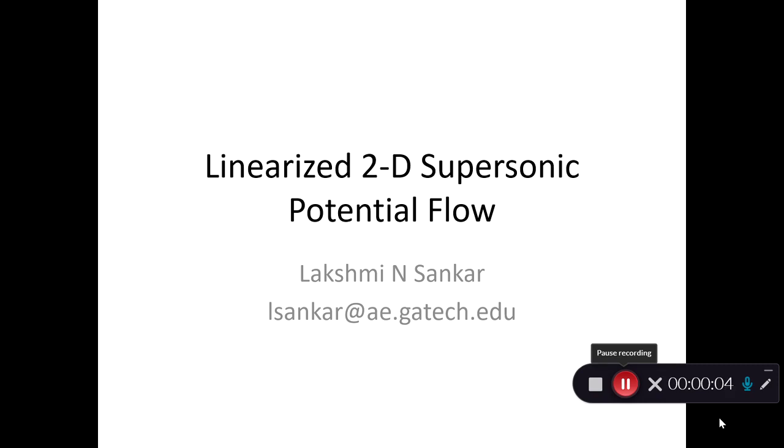Good morning. Today we'll be talking about linearized 2D supersonic potential flow. In a previous module, we looked at subsonic, even incompressible potential flow. We said that potential flow can be modeled using a number of building blocks such as sources, sinks, doublets, and free stream. Then we made small disturbance assumptions and we developed something called thin airfoil theory.